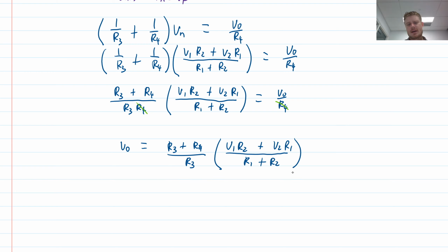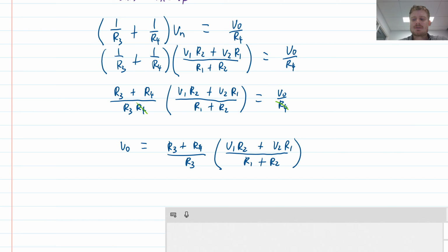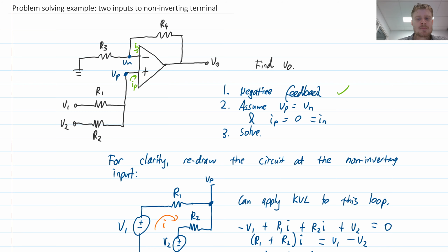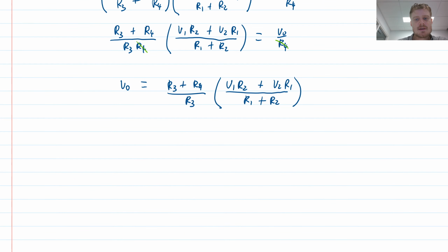So I guess taking a step back, what is the purpose of this, or what does this tell us? Basically, if we had an op-amp circuit like this one here, and we wanted to use it to combine together, to mix together these two different signals, two different voltages, so to mix together V1 and V2 in some way to produce an output voltage, and we also want to amplify them, then here is the design equation that describes that relationship. So we choose values R1, R2, R3, and R4 in order to get the correct amount of mixing and amplification that we want for a certain application.